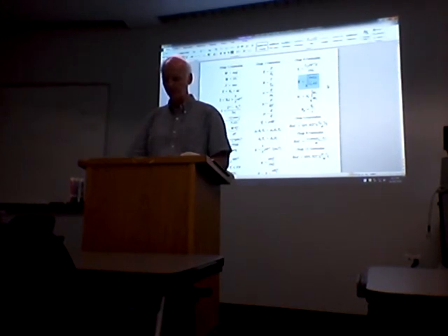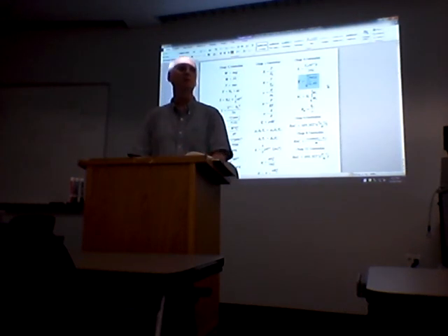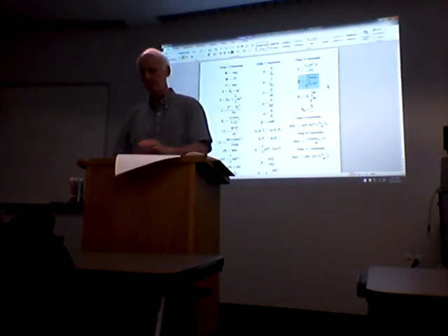For power-producing aircraft, L over D max gives you max range and engine-out glide ratio, but not max endurance, which it does for the jet, because that point is not the minimum drag point. That's the difference between jet and propeller.